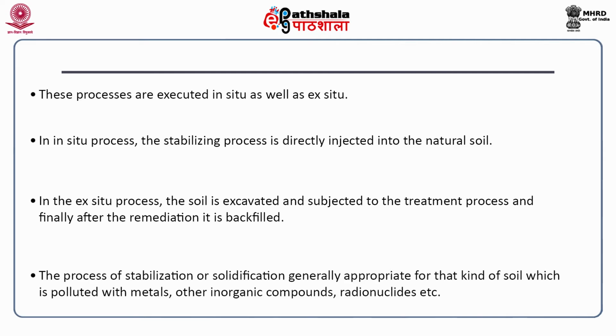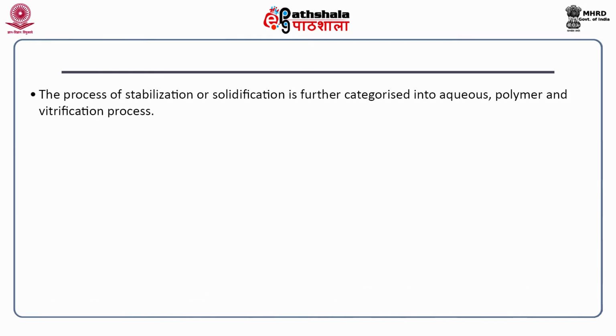The process of stabilization or solidification is generally appropriate for soil which is polluted with metals, other inorganic compounds, radionuclides, etc. Volatile organic compounds are usually not preferred for this process because VOCs have a tendency to evaporate into the atmosphere during the process of mixing. The process of stabilization or solidification is further characterized into aqueous, polymer and vitrification processes.